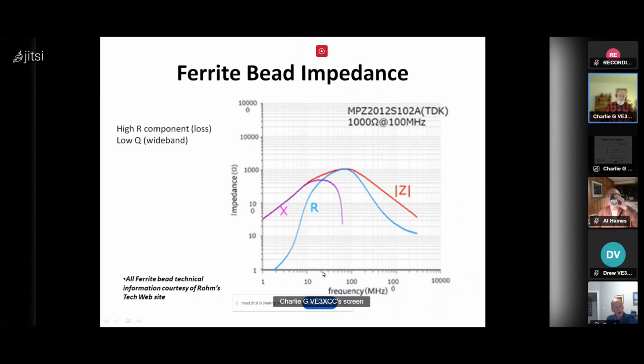Then as you start to drop down, get down into the 40 meter area, well, not so great. You're probably looking at 20-30 ohms at most per ferrite bead. So, as the frequency goes up, these things are definitely much higher value for you. For HF stuff, I think you're better off using a toroid and looping a physically smaller coax through it as many times as you can.